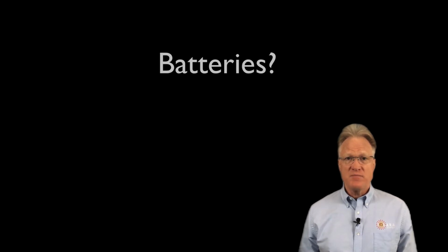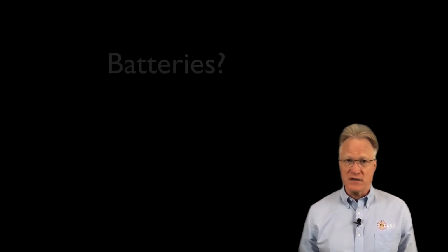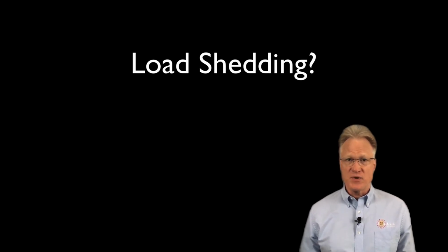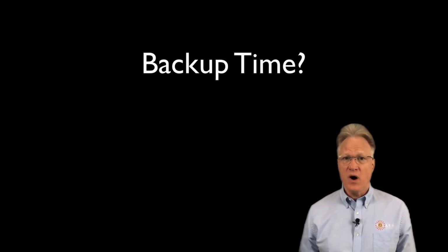If you need to add battery backup, what percentage of the load do you want protected? If less than 100%, do you want a load shedding feature like a low voltage load disconnect? Usually, not every load is critical. How much time do you want the batteries to hold up the load? 2 to 8 hours is typical.